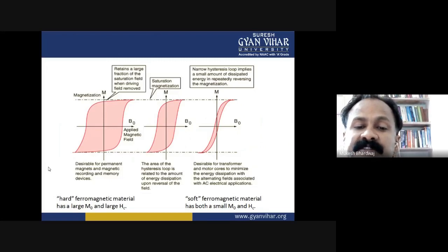The shape of the hysteresis loop of the magnetic material is of great engineering importance. Soft magnetic materials are easy to magnetize and easy to demagnetize. This enables them to reverse magnetization rapidly in response to an alternating field, where they are required to concentrate magnetic flux in transformers and inductors. With an alternating current of frequency 50 Hz, the core traverses the whole hysteresis loop 50 times a second.